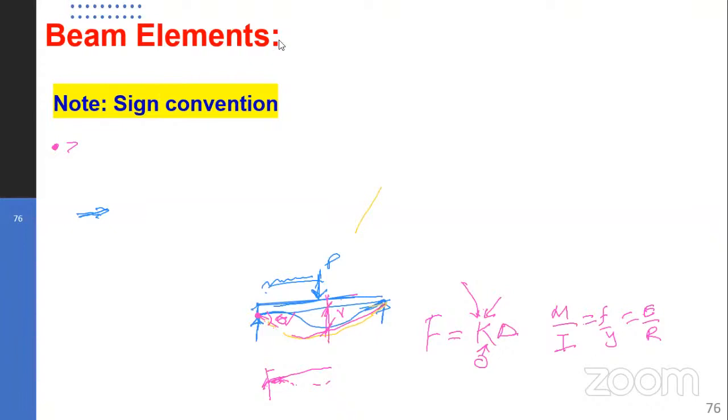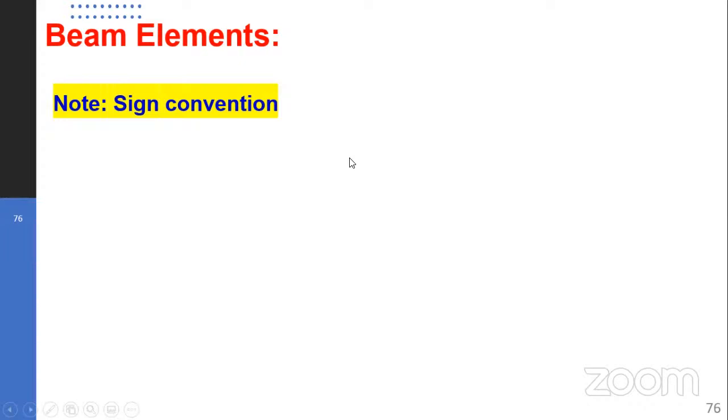So before we come to the sign convention, this is our beam. The beam is loaded only in the y direction. We have this axis as y, and this as x. So the loading will only be transverse. Then number two, the deflection of the beam is small in comparison to the characteristic dimension of the beam. So we are talking of small deformation.